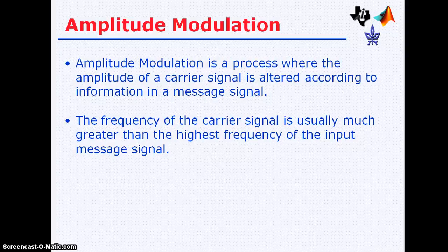This modulating signal is basically the information signal which is received as an output of a transducer to convert a particular information variable into electrical form. Now in modulation, what is required is to change. In case of amplitude modulation, the amplitude of this carrier signal is to be changed according to the information signal or baseband signal or modulating signal. So we have got basically amplitude, frequency and phase as the three properties of any signal, and any of these three properties can be altered or used or changed according to the modulating signal.